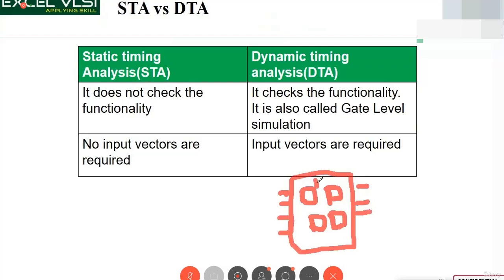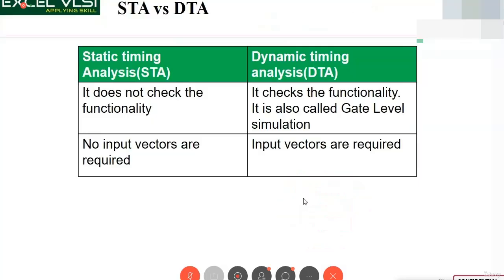where you see that if this is the processor, from the processor whether the path is okay. All these, you select some test cases for each of the data paths and then run in gate level, right? And then make sure the functionality is okay with gates with delays. Okay, that is dynamic. And you apply test vectors. That's what I wanted to tell.